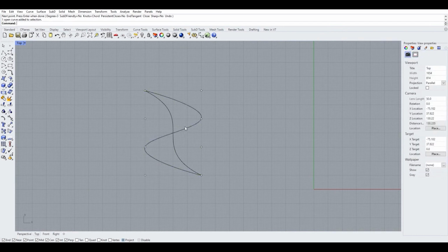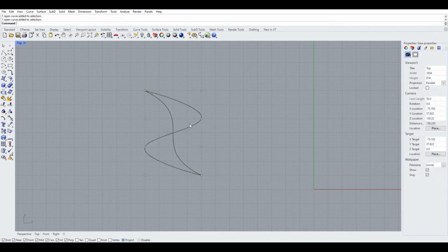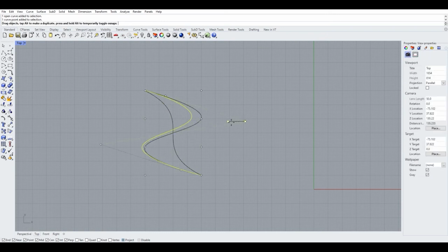Now, also, while I'm busy with this, you'll see that if you select a curve, you also see the points that define its shape. So if you want to edit the shape afterwards, you can simply click on it and then click on those points to alter the shape. You'll see my ortho is on, so I can only move in 45-degree angles from my original reference point, but I can change the shape afterwards if I'm not happy with the original. So that's the big difference between the control point curve and the curve interpolate points tool: we use the same points, but we get a completely different result from them.